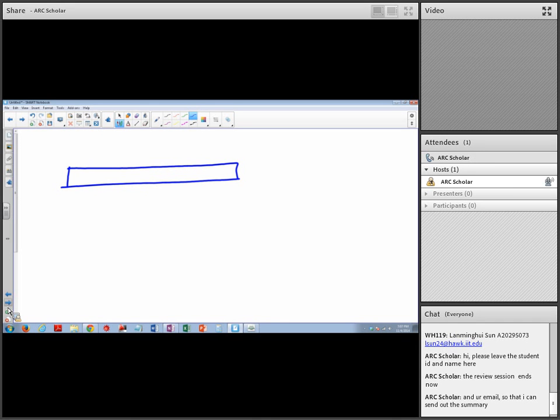For the singularity method, you need to memorize a few things. So the first one is when there is a force, it is going to be x minus a to the power of 1.